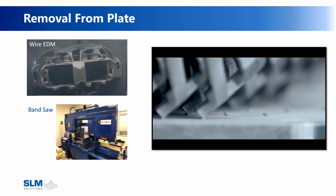Next is removal from plate. What we see here is three separate ways that we go about removing the parts from plate. One, wire EDM. This creates a very, very clean cut, almost a finished surface cut. One thing is it's very slow and it's a very expensive system.